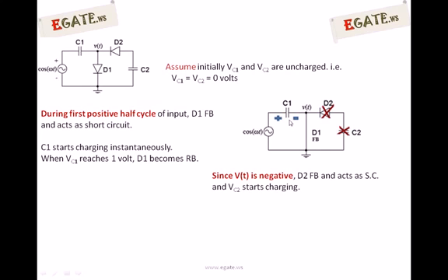So this minus 1 dominates for all the values of cos omega t. Even though the maximum is plus 1, the voltage V of t is 0. It is not positive. So this effective voltage may be either 0 or negative, which makes diode 1 reverse bias and diode 2 forward bias.